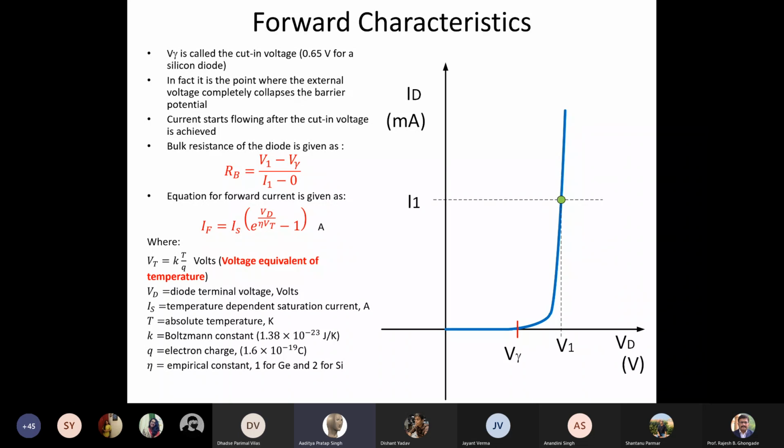Yes, sir. Okay, now if I want to capture the effect of temperature, what will be the effect of the temperature on the conductivity, that is the mobility, diffusion? That relationship is captured by this particular equation, which is Vt is equal to kT by q. It simply means that as if I am applying so many volts, because of the temperature, the effect will be a similar one.